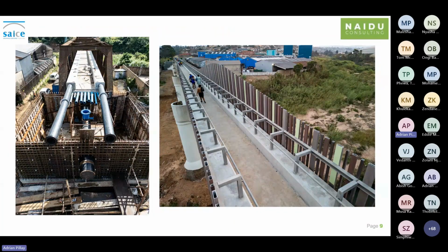Careful selection of the types of materials and the construction approach ensured the bridge was durable and vandal-resistant for long-term performance with minimal upkeep. For example, the selection of HDPE pipes encased in concrete requires little to no maintenance and has little to no monetary value for theft. The deck over the piers was made continuous, eliminating the necessity for expansion joints and the maintenance thereof.